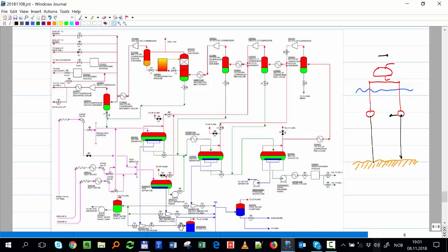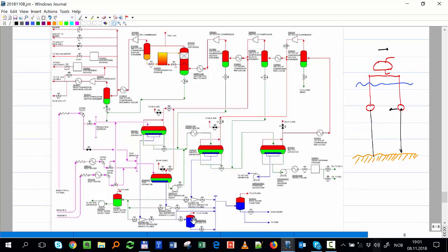And where does that go here? To EPCON CFU. What is that? What did we have? A combination of hydrocyclone and flotation, right? This is where you introduce gas and it flows up and takes out the bubbles. So this CFU is a compact flotation unit. I'm not going to write it, but if you want the acronyms, you can write: compact flotation.